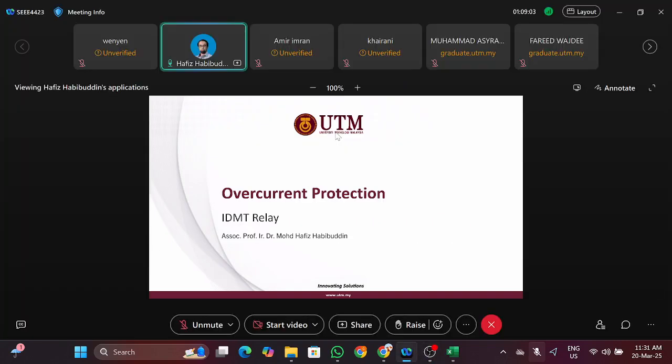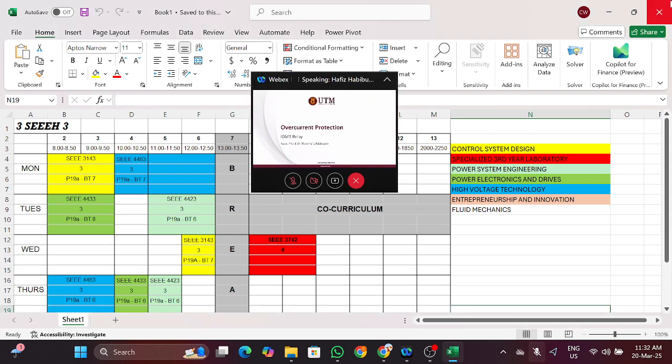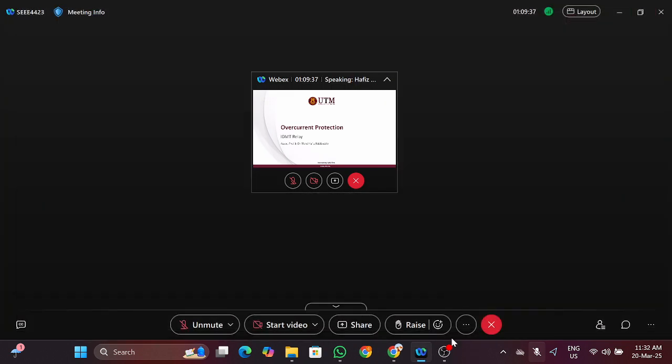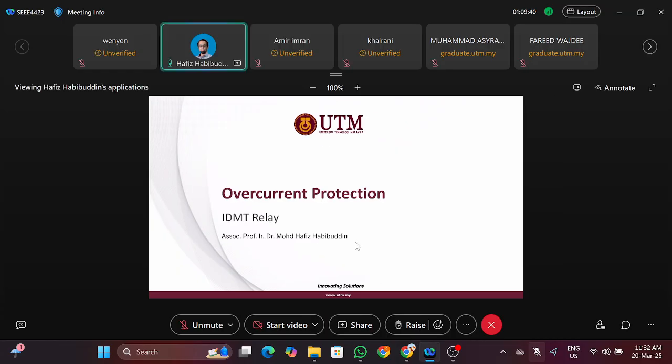Voltage for the VT accurately, now the current will be fed into your protection relay. The relay is the brain, which will decide whether you are facing a condition of fault or not. So there are various configurations: overcurrent protection, distance protection, and everything. Our focus now is on overcurrent protection, usually used to protect a distribution feeder coming from the distribution in your substation towards your own load.